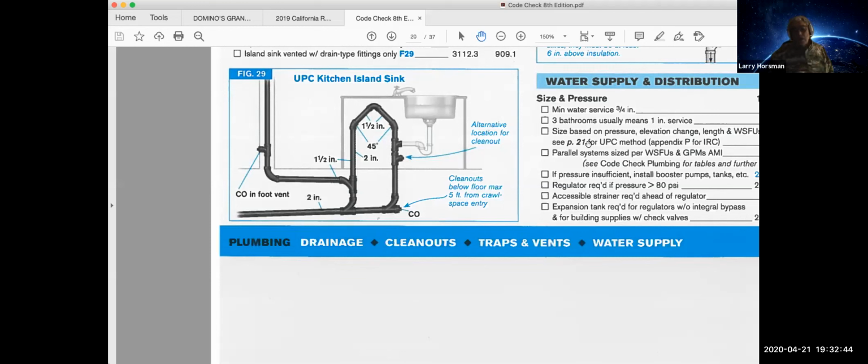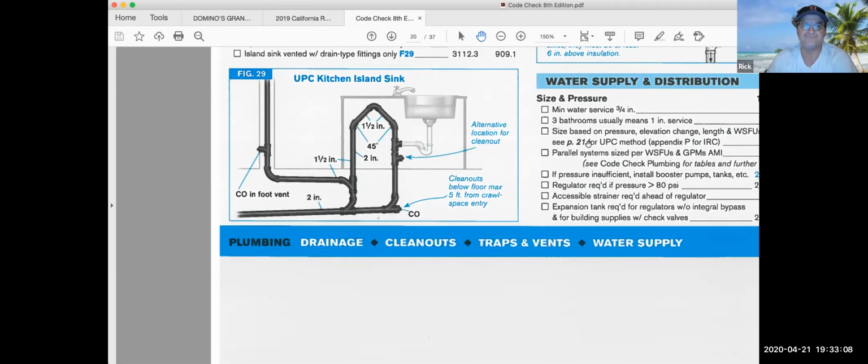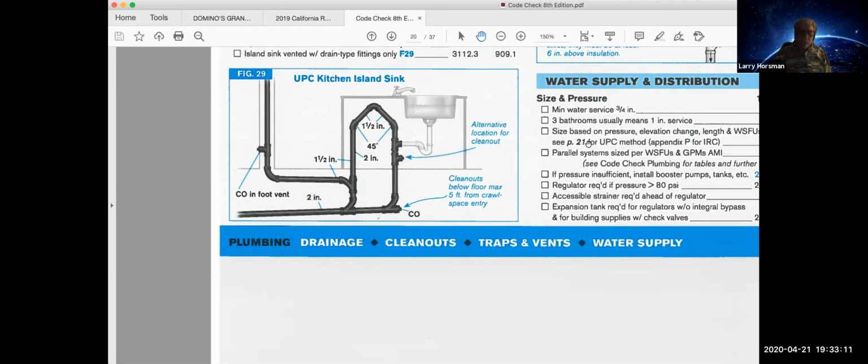So if you're going to put in a water service, normally you go to the engineering department and they give you something called a water service data card. That water service data card gives you both the maximum and minimum static pressure at the meter, because the water pressure goes up early in the morning. It goes down when people are getting ready for work. By early in the morning, I mean 2, 3 o'clock in the morning, the water pressure goes up. Not a lot of people using the water. And then during the day, during periods of peak demand, the water pressure drops.